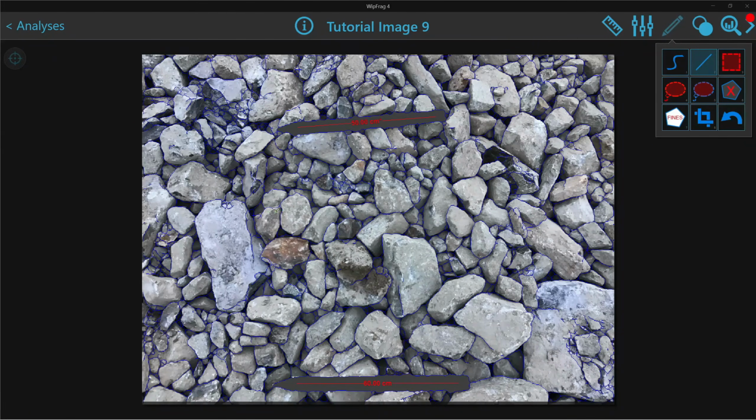Draw Line. Click and drag to begin drawing a straight line between the starting point and an ending point. Box Delete. Click and drag to begin drawing a square or rectangle. Any net within this area will be deleted. Lasso Delete. Click and drag to begin drawing a free-form shape that will close itself in. Any net within this area will be deleted.